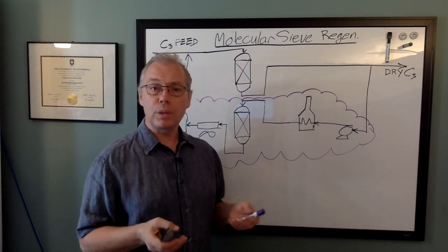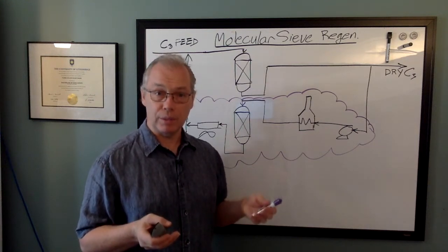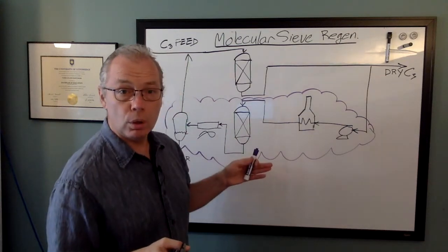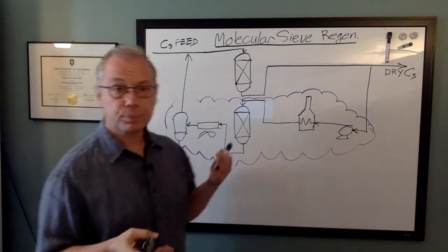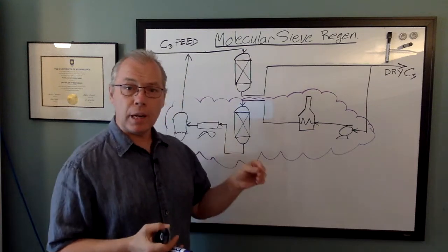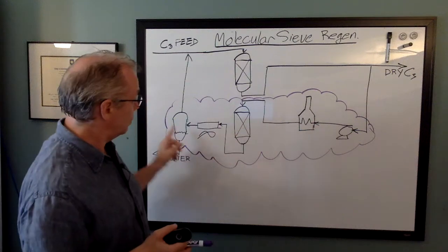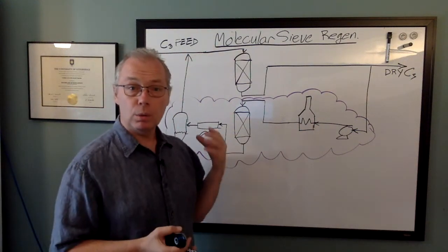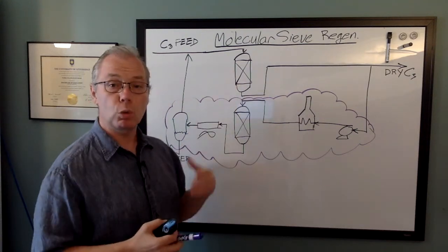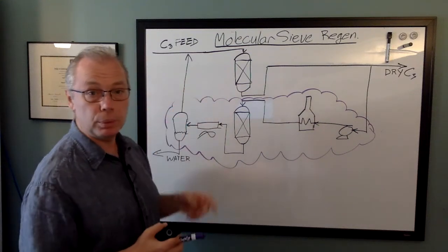The one that we're going to consider today is modeling the regeneration phase for a molecular sieve dehydration system for a liquid hydrocarbon, shown here. The case that we're interested in is understanding the cause of a large surge in liquid flow that comes back to the combined feed that goes into the dehy tower right here. So when the regeneration phase begins, there's a large surge of liquid.